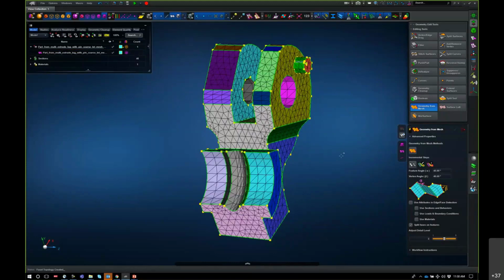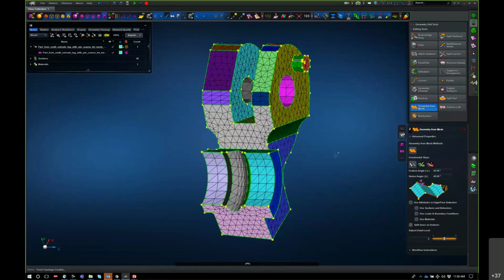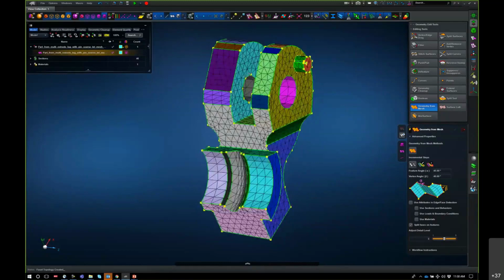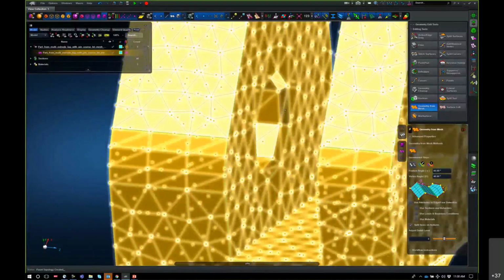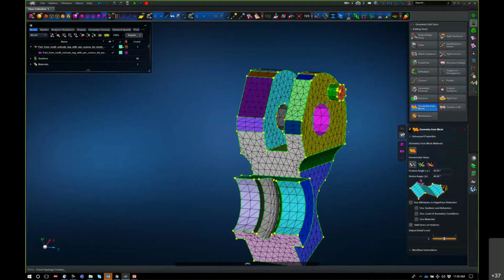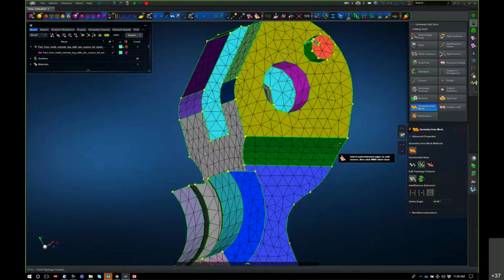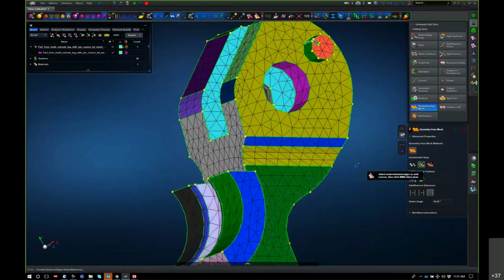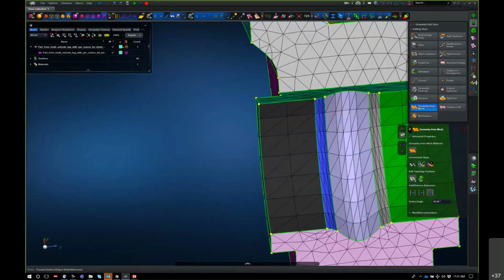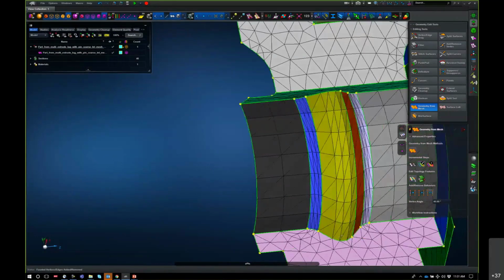It's very similar, but the difference is I lost my chamfer in this hole. I lost an edge along here. So of course I can come in here using the tools. I can click on this edge, Alt double click, and there's my split there. I can continue to split it up. Great tools we have now. It's much easier to work now because I have visual picking turned on. I can add on my splits.